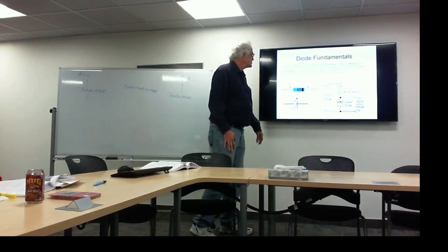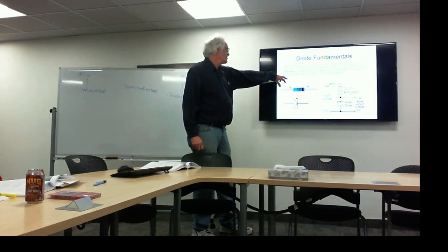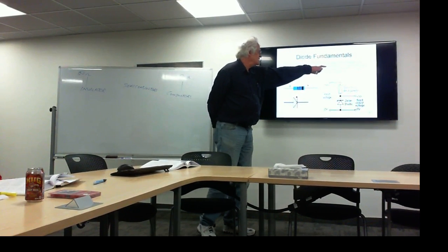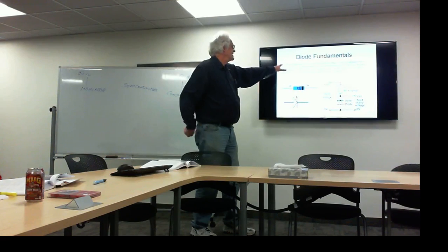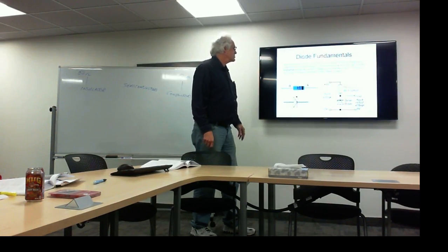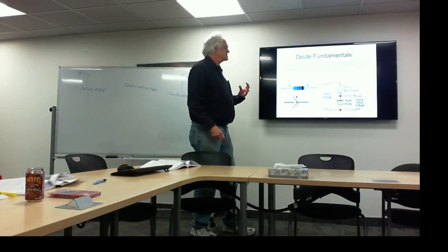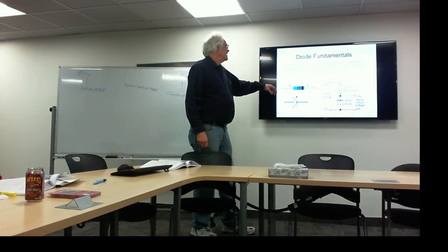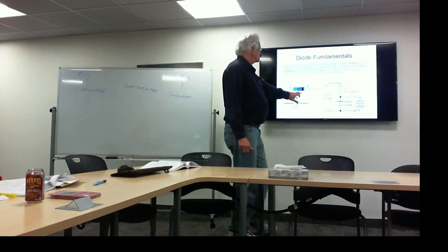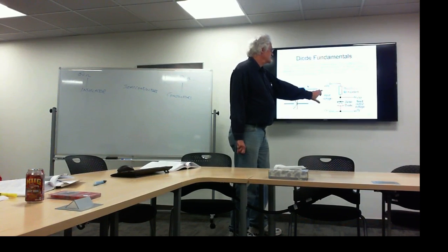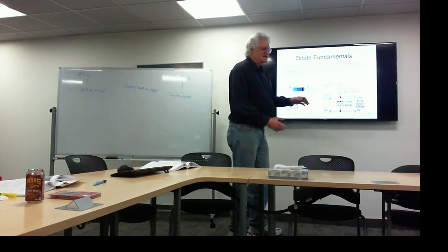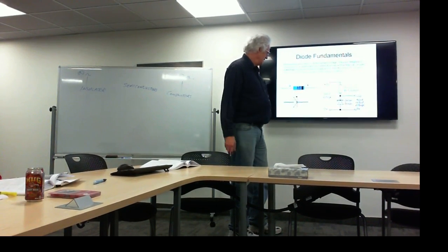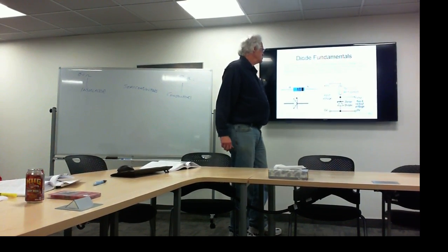With the one exception being what they call a Zener diode. It's actually designed to, well, they say in brackets, break down. Well, it doesn't destroy it. It actually will conduct in reverse at a certain voltage. So a Zener diode has a rating which is called a Zener voltage. It will actually conduct in reverse at that voltage. We can use that to our advantage.